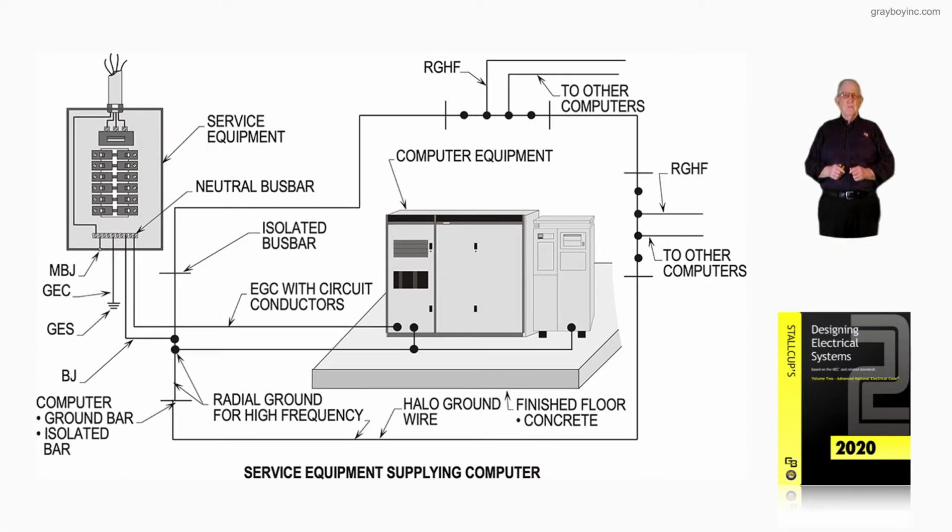Now this illustration deals with computer grounding using a spacer, in accordance with NEC 250.96(B), but it also could be used in accordance with 645.15 in some cases. Now notice the note, we are trying to accomplish an equal potential plane.